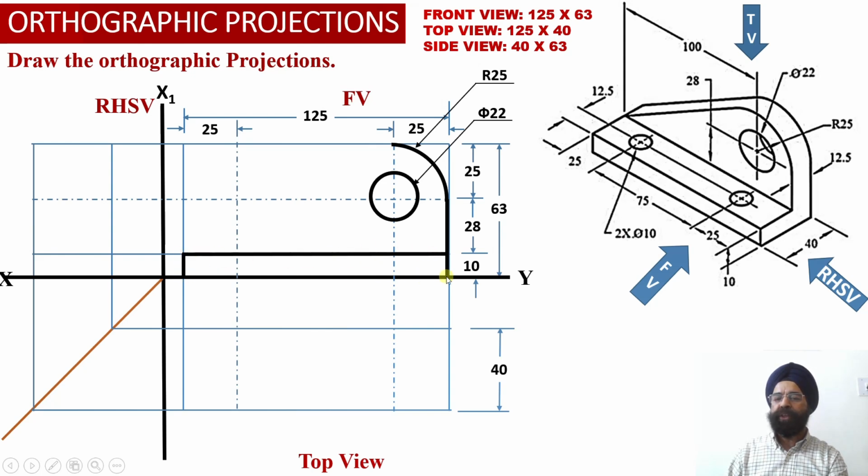So the projections corresponding to element number 1 have been obtained, and now corresponding to the circular portion we know that there is a vertical face available onto the right hand side face of this particular solid. So this vertical web will have a perpendicular face towards the right hand side surface of the solid. So now we have obtained the vertical projections corresponding to this vertical edge.